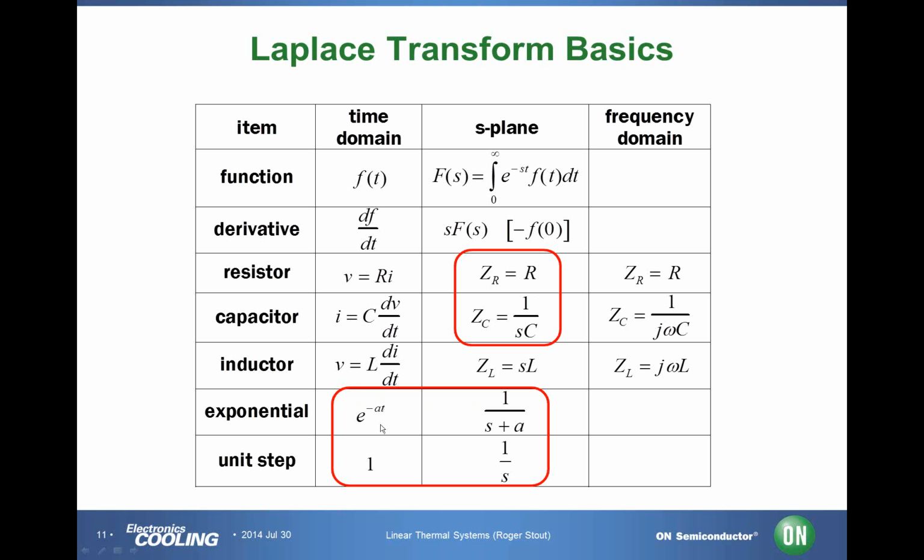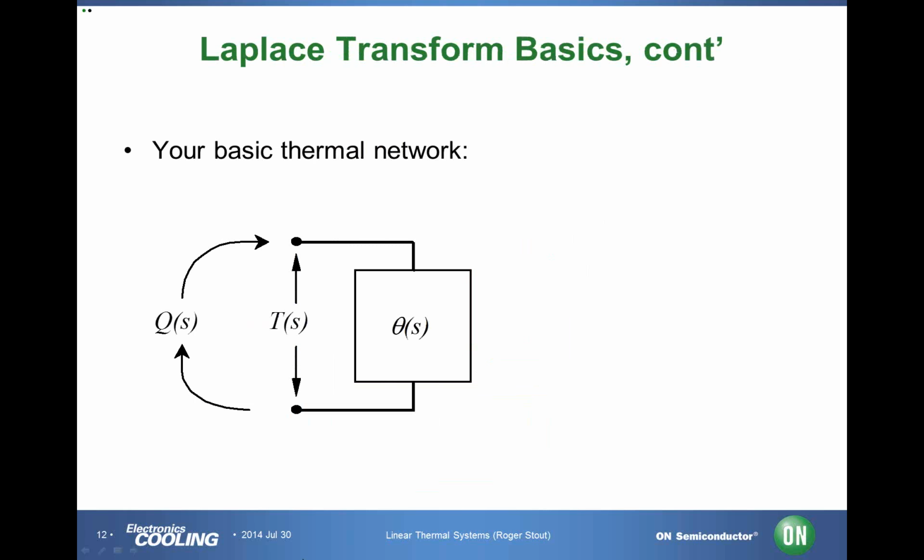The responses that we're interested in are exponential responses. The unit step has a Laplace transform of 1 over S, and an exponential response in time has a Laplace transform of 1 over S plus A. These become important to know because as we manipulate Laplace transforms, basically everything we're going to do will result in an exponential response.